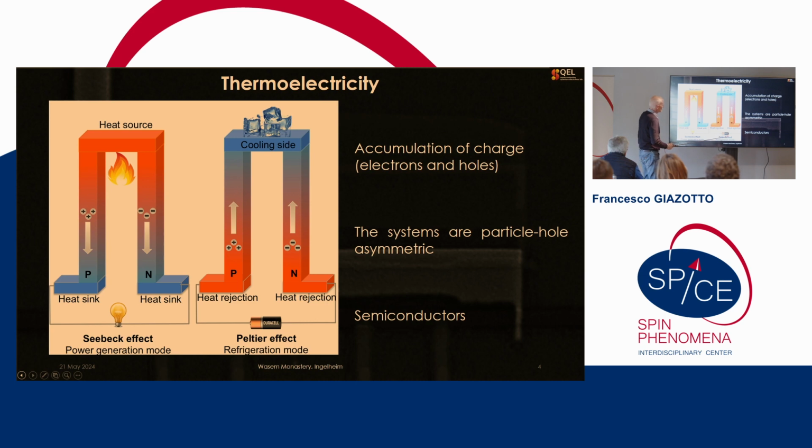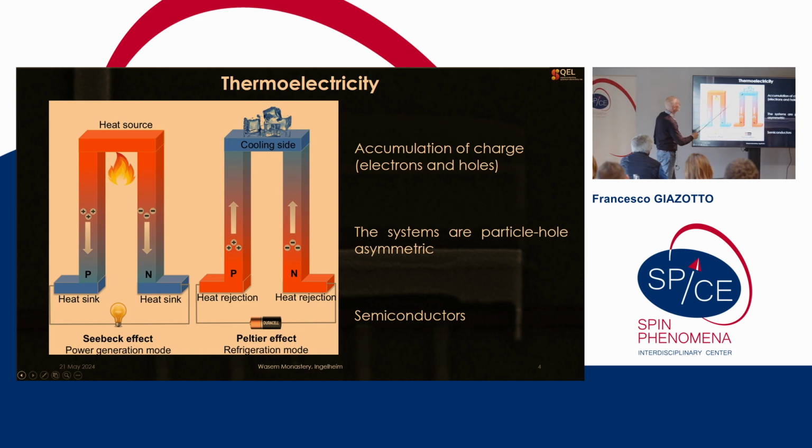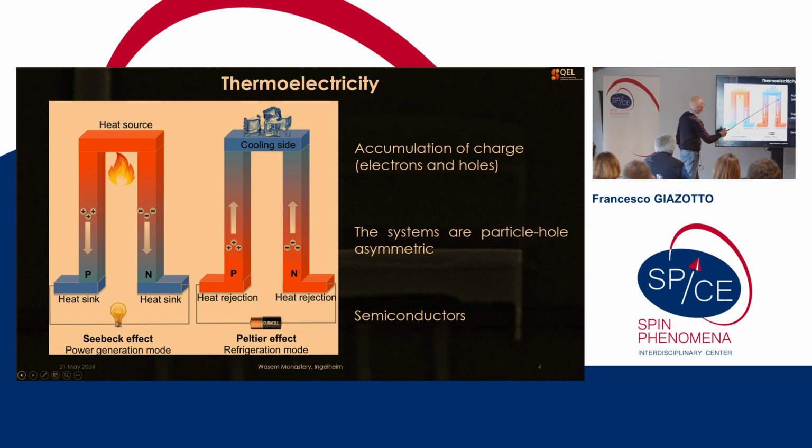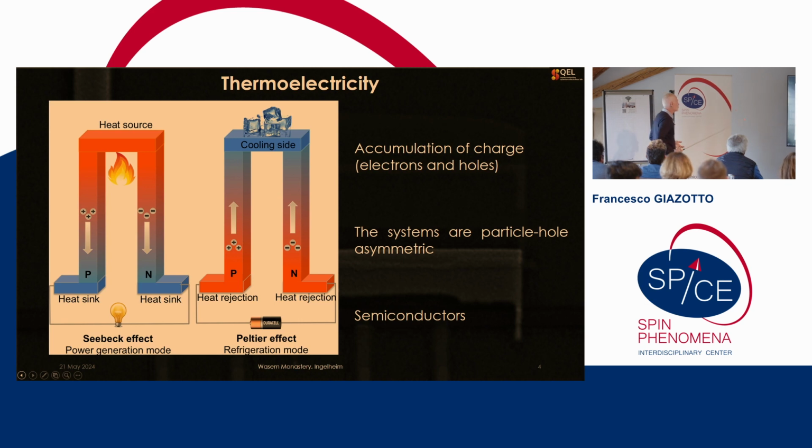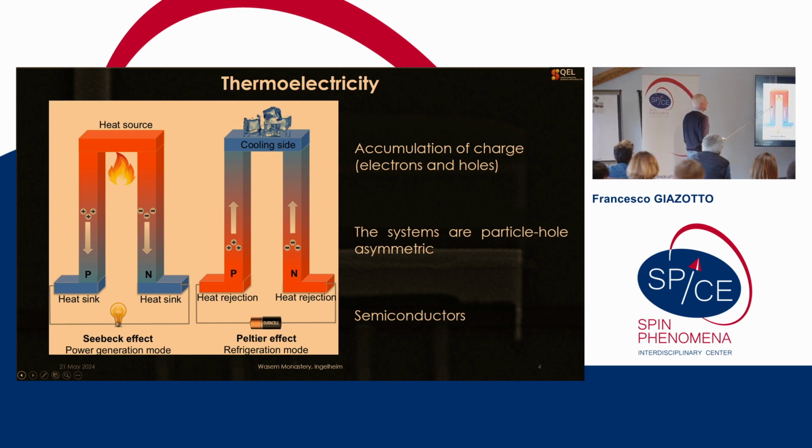The opposite effect is the Peltier effect, as you're seeing. So, for instance, in the refrigeration mode, we can anchor one part where we have a heat rejection, and by driving a current in this circuit here, thanks to the Peltier effect, we will cool the other side. So Peltier coolers are, again, very useful for many applications where you want to avoid any vibration, okay?